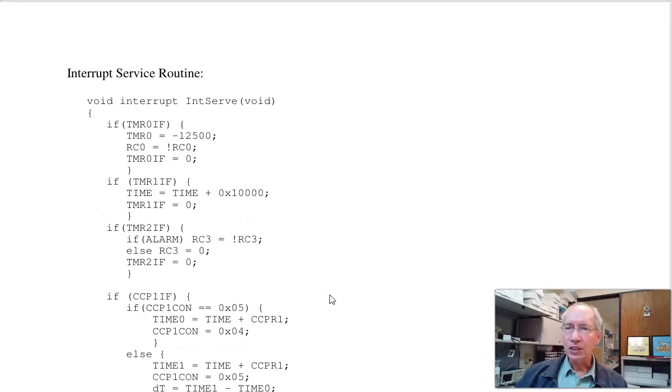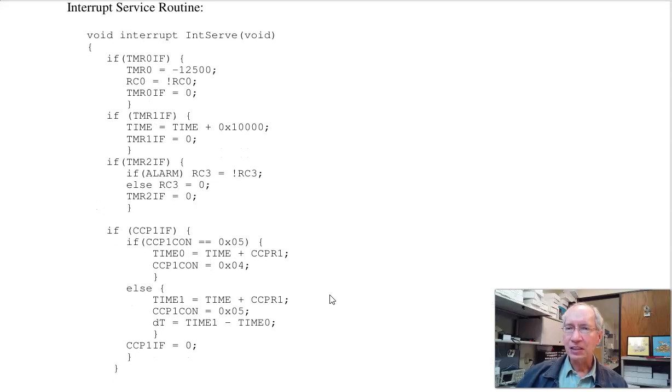What the code looks like is I've got actually 4 different interrupt service routines running. Timer 0 is outputting a pulse every 100,000 clocks. So this has a prescaler of 8. N is 100,000.